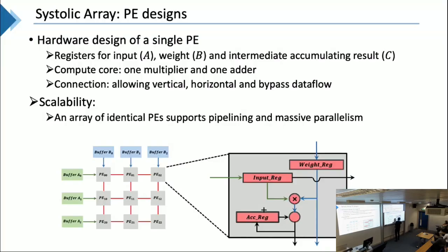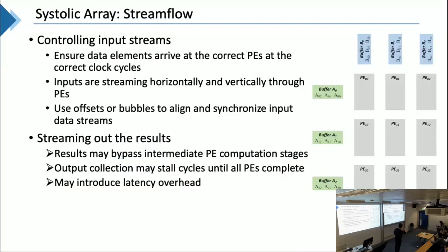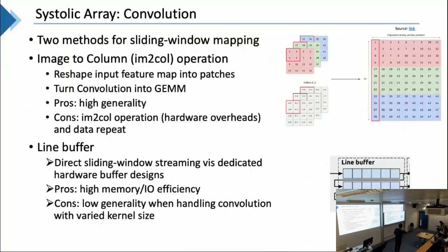So if you use different data streams, you might need to change this basic PE unit. But you can also design your PE unit to make it reconfigurable to support different data streaming or stream flow. So this is the basic of systolic array.